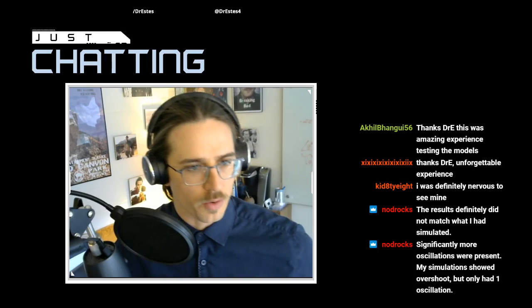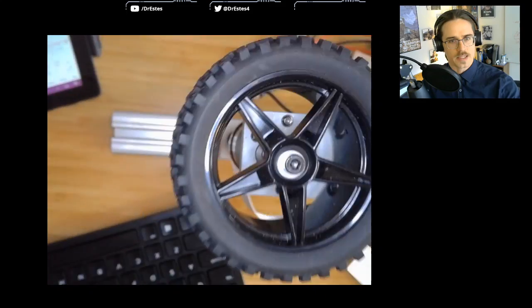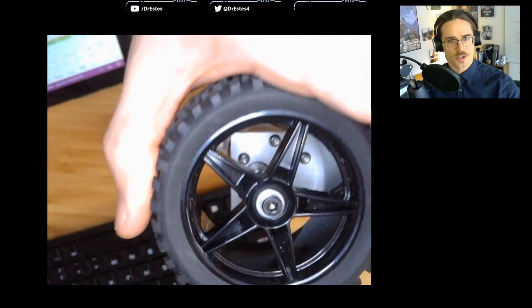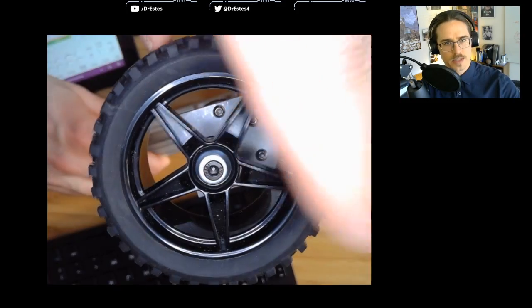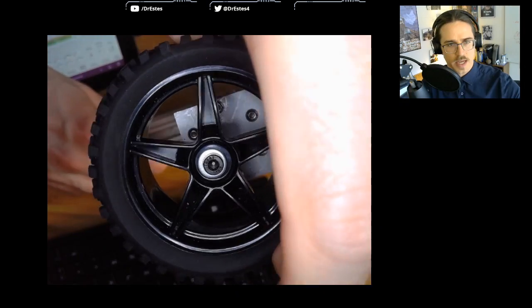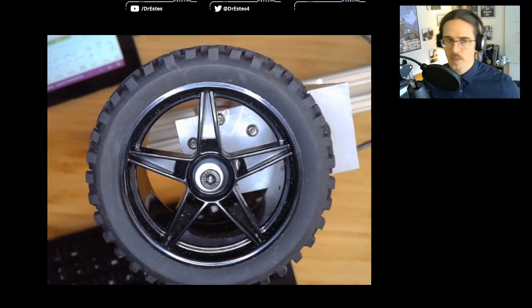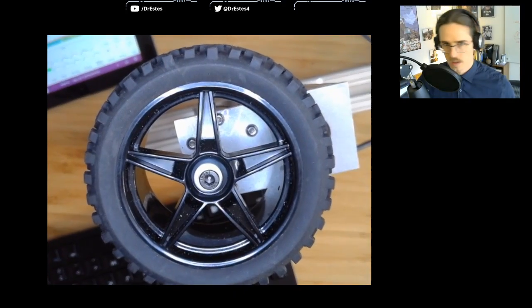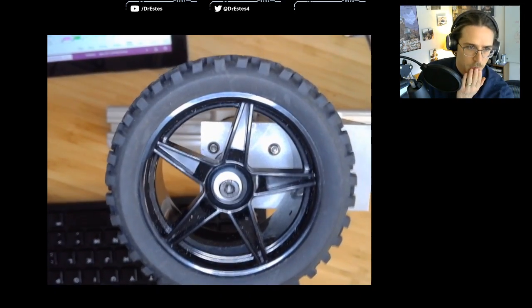We're using a little cheaper setup, but totally normal to see a bit of difference and then just compensate for it. Because some of those differences, they don't show up in your simulation. You can't know until you actually run it on the hardware. Like, we know for this DC motor that it has some asymmetries in it. If you spin it one direction, basically it spins differently in this direction versus that direction. The same voltage will result in different speeds depending on the direction. So it's hard to capture stuff like that in just a linear model.